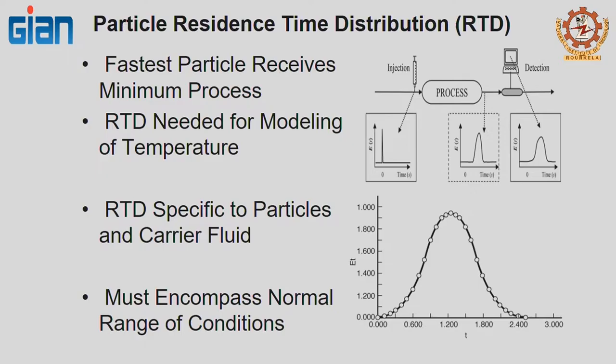So, here we are getting into a little bit of a food engineering or chemical engineering concept, the residence time distribution. Basically, the concept is, I mentioned here, you inject 100 particles, you pass them through a holding tube, and then you measure how many particles come through. Ideally, all the particles would come at the same time, but this is almost not practical. This is more practical.